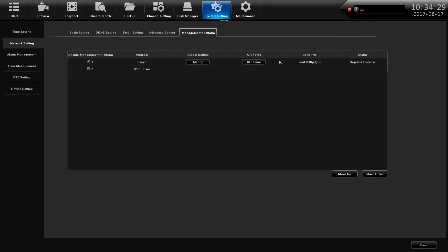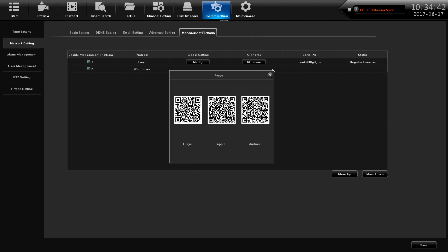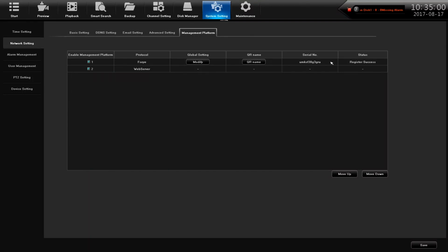From the next screen you can select a name for your device, so Ben's Home NVR for example. The next line is the device information or device ID. So if you tap the QR code that's on that line and scan this QR code here on the left hand side, the device will talk, we'll see each other. Then you'll need to put in the username and password, admin, and the password 888888 or whatever you've chosen, and then you're ready for remote viewing.